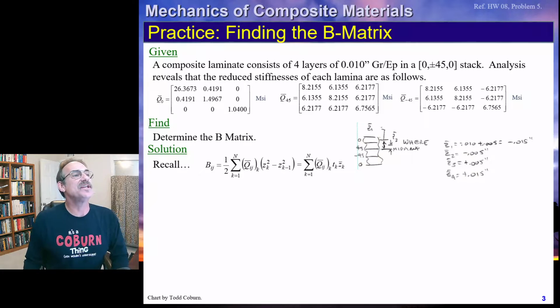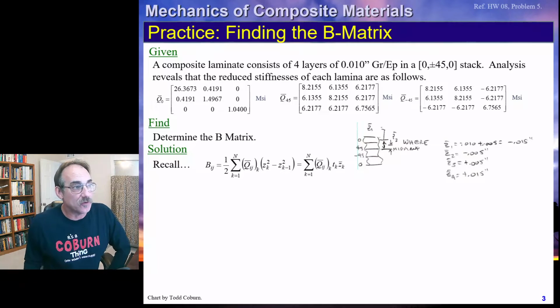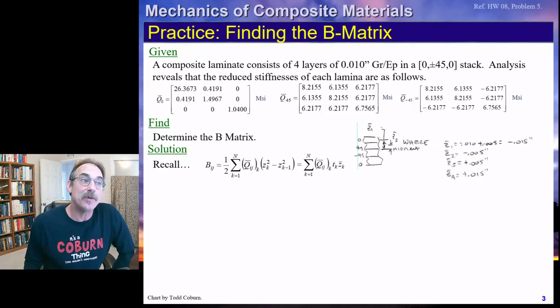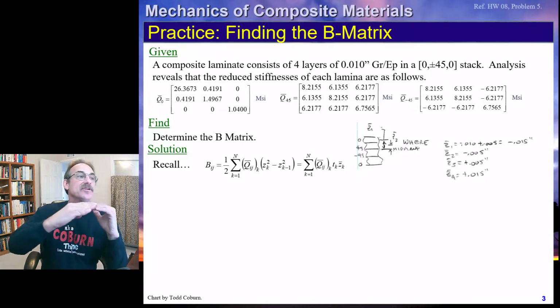So these are our Z bar parameters, and if you're doing this analysis, it is useful to first sketch the composite laminate, to sketch the dimensions you're going to be using, and then compute them, and then look to make sure they make sense. We can see Z bar for the topmost element is up here,